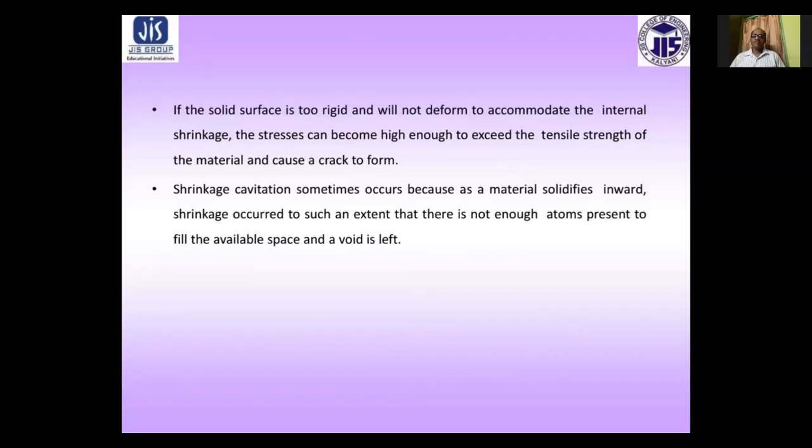Shrinkage cavitation sometimes occurs because, as material solidifies inwards, shrinkage occurs to such an extent that there are not enough atoms present to fill the available space and a void is left.